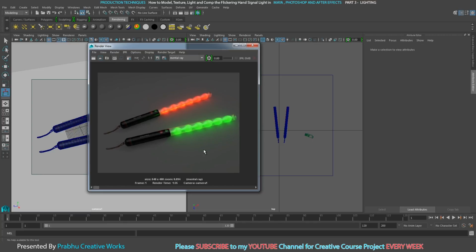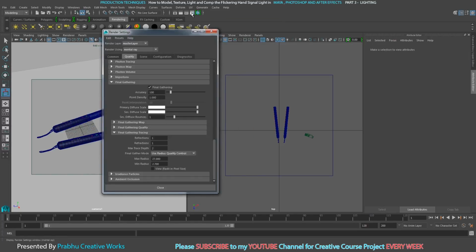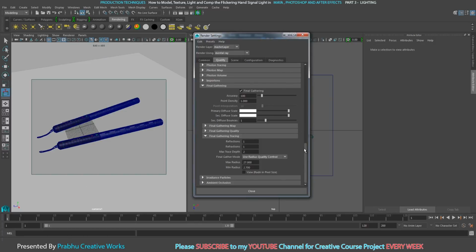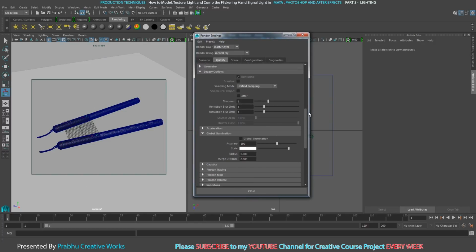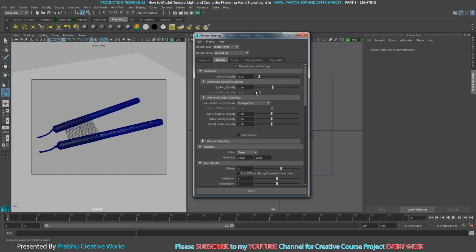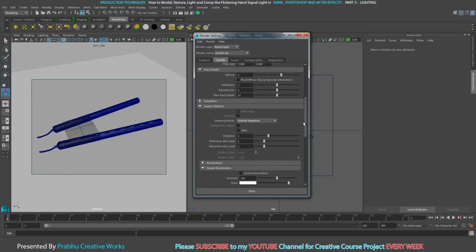So before we take the render, we want to set the animation and change the width and height. So first of all, change our width and height. Go to render settings. Here you want to set the sample level. See here, overall quality we have set over here, and then you want to give some sample level.